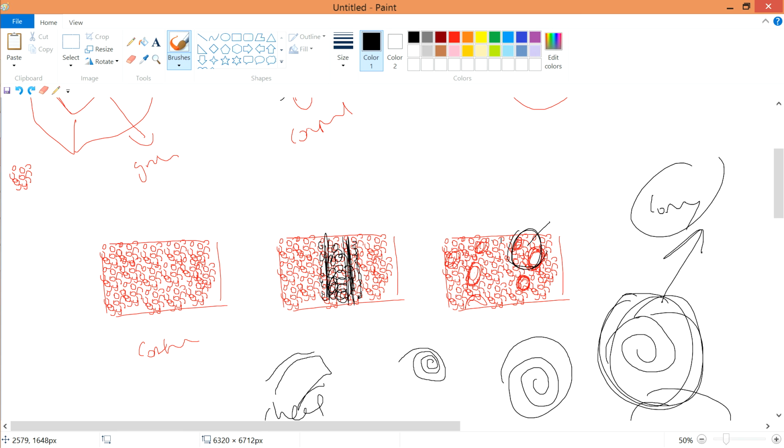So in other words, the stress distribution is not good when the grain structure is not consistent. Sometimes the stress at this point and this point is different, and therefore it may create a crack in between due to the difference in stresses or difference in temperature, and thermal expansion, things like that. At least you get the meaning of that. If you have a very fine, controlled, consistent grain structure, the stress distribution will be very good.